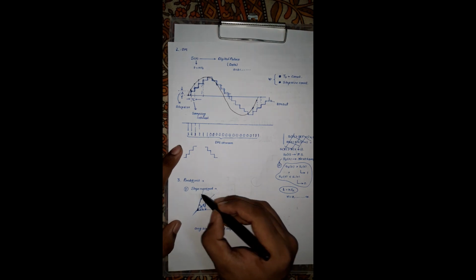So that's why we can say that the input signal slope is overloaded on the DM output signal slope. Okay, why is it overloaded? That means the signal slope is too high for the delta modulation to follow exactly.